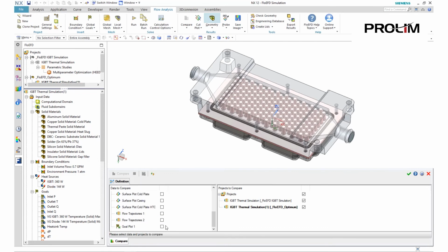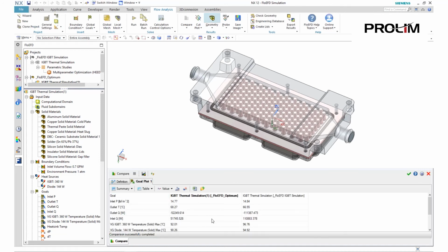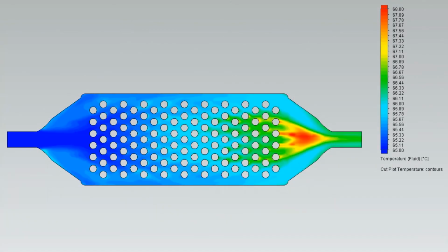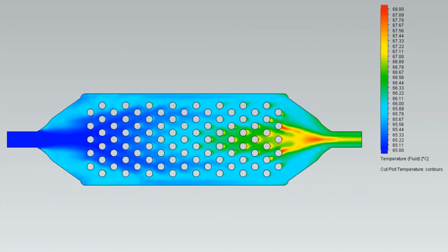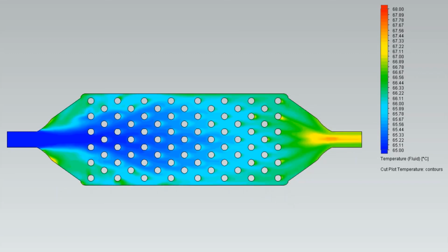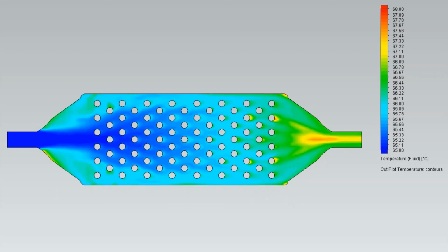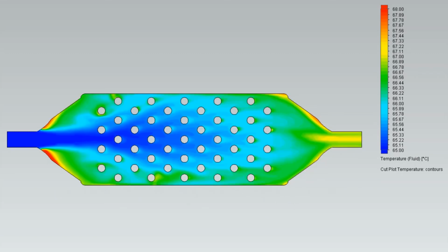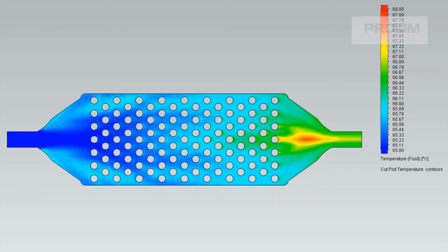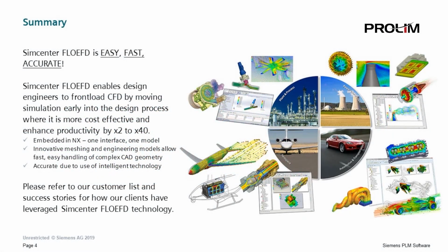We can also use the numerical data to compare the results. From this table, we can see clearly that our maximum temperature drops and the delta P decreases as well. Performing this parametric study, we can obtain not only one, but several optimum designs, allowing the user to take this newfound knowledge to look into the possible trade-off of IGBT maximum temperature and pressure drop of the cooler.